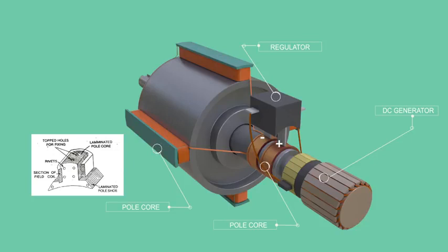Voltage regulation can be easily achieved by controlling the field current. If terminal voltage is below the desired limit, regulator increases the field current. This will result with increase in terminal voltage. If terminal voltage is above the specified limit, the reverse is done.